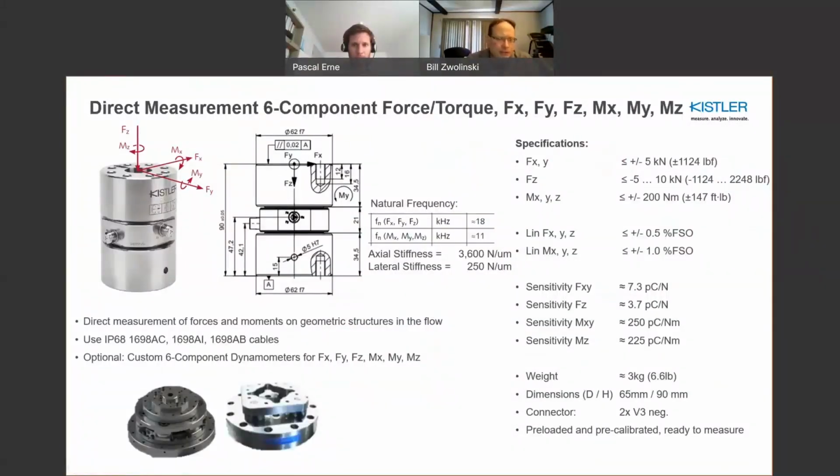I talked previously about multi-component force. This is a 6-component sensor, and you see it's actually got a through hole. You say, well, that can be used in maybe prop shaft measurement. Well, not quite yet. It's a charge mode output. Yes, it could use the inline 3-component amplifiers I just showed you before.